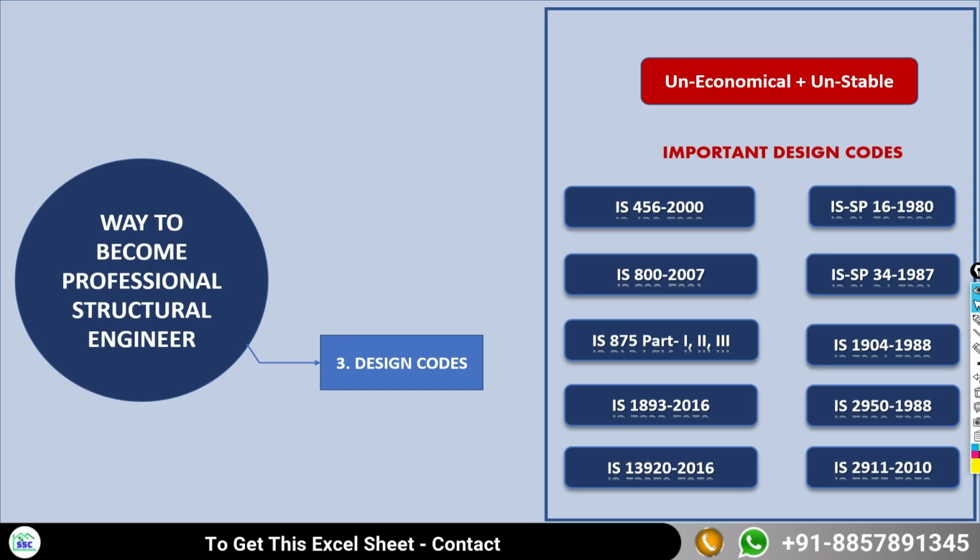Then you need to know what Part 1 and Part 3 are for. If you want to assign the earthquake loading, which code do you follow? IS 1893:2016. If you want to do the ductile detailing, IS 13920.